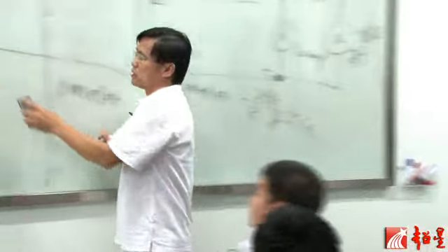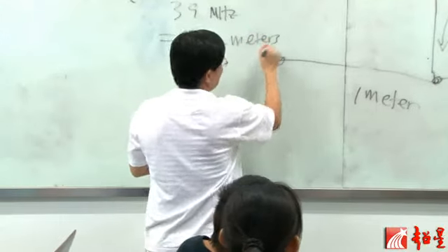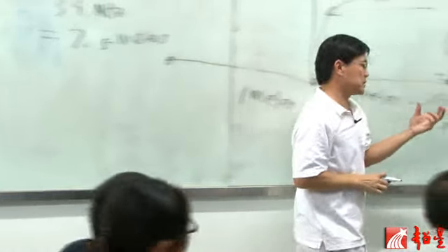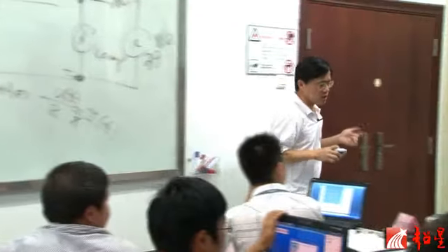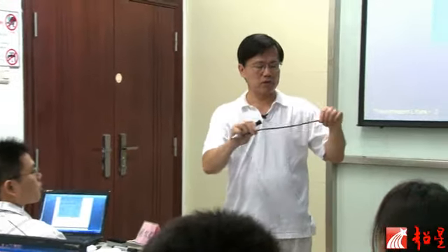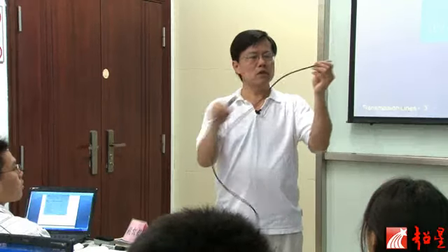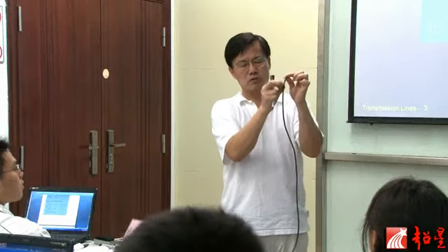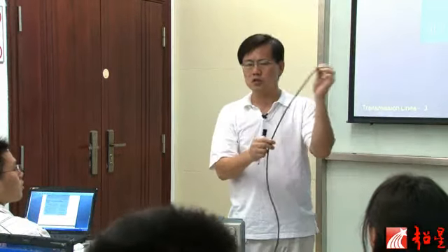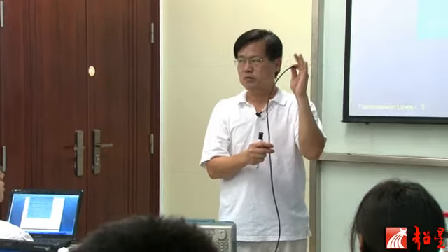But in a cable, most cables are so-called 60% cables. Some cables will tell you the speed of the cable. This one doesn't have any marker. So usually the speed at which an electromagnetic wave travels inside the cable is much slower than the speed of light. It's about 60% of the speed of light.